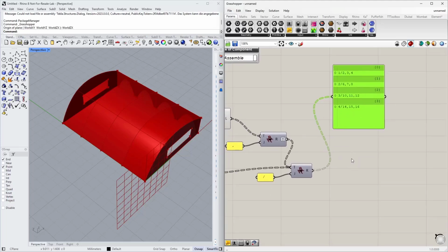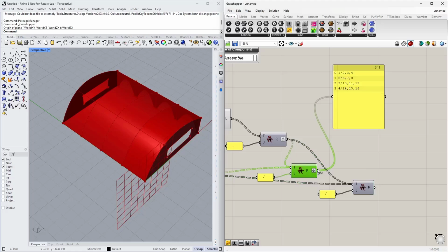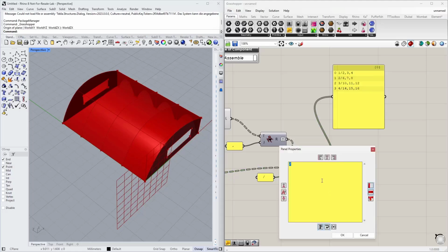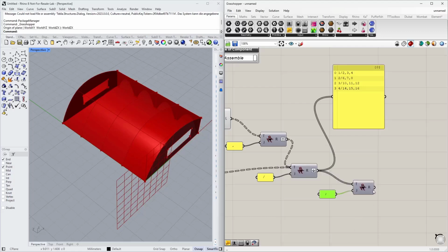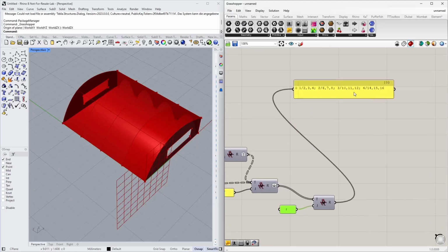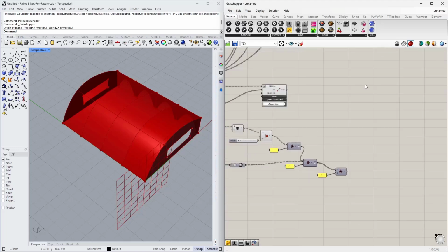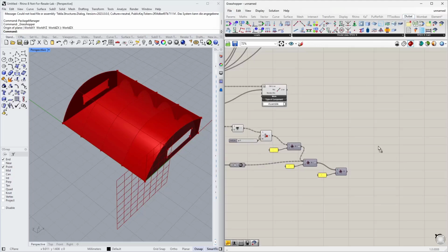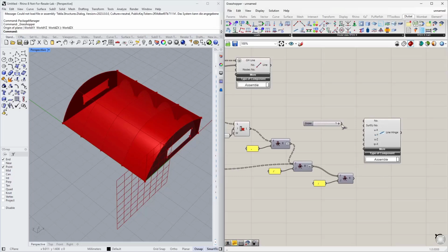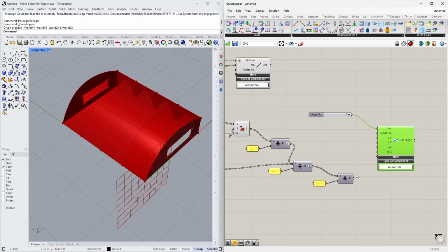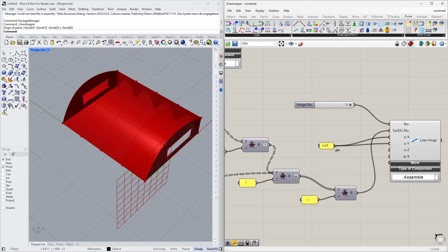And now I need it in one long string, that's my requirement at least. So I will flatten this result and join it by a semicolon and a space. Okay, and now the result looks like this. And this is exactly how it looks in RFEM. So far so good. Now let me use a line hinge component, assign a number to it, assign this string that I just created, and define the connection. So I would like to fix all forces in each direction and release the rotation.